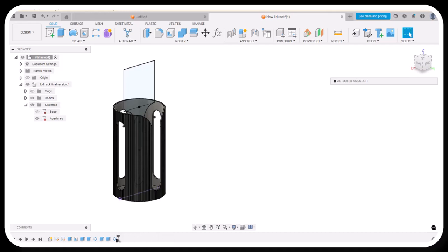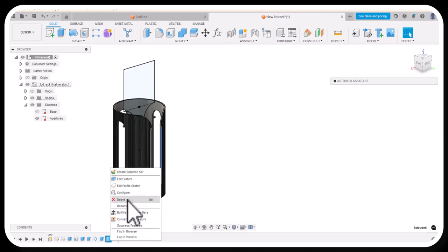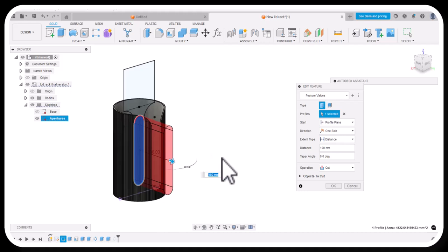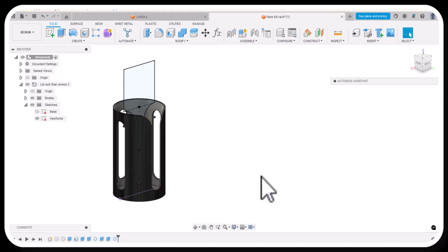And again, on this extrusion, I'm going to make sure that it goes beyond, not just to that edge, but beyond that edge by some distance. And again, you can make this a function. Let's say D1. That was that original diameter. D1. So it'll go out. Remember, it's going out from the center, so the radius is going out that diameter distance. That'll make sure that it always goes through the entire object.